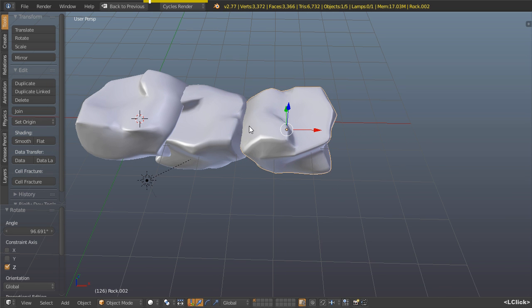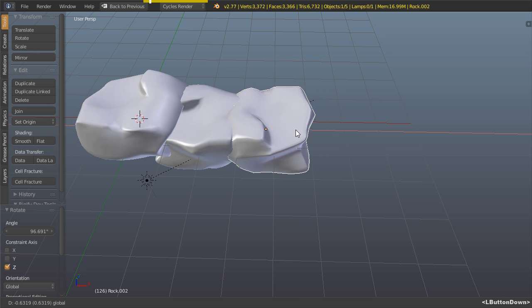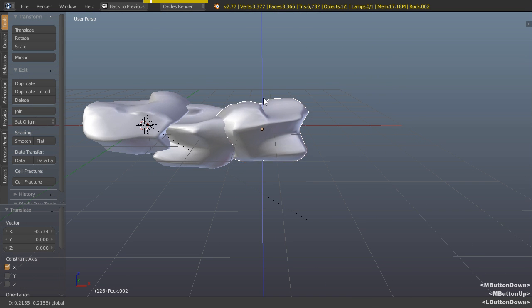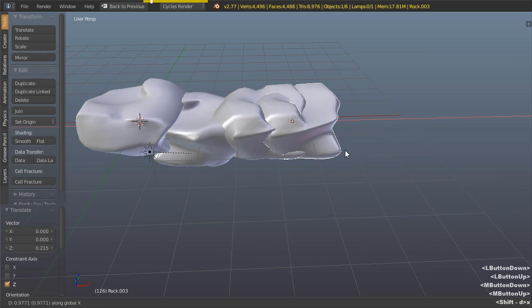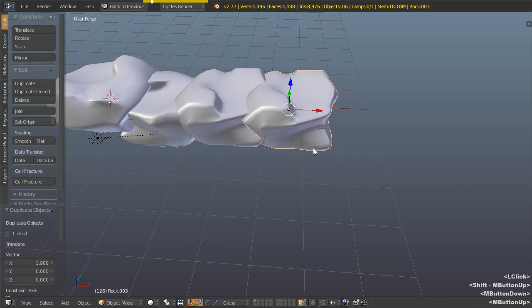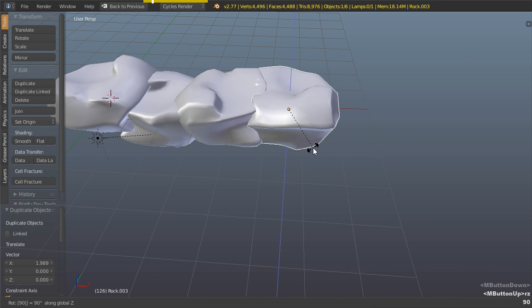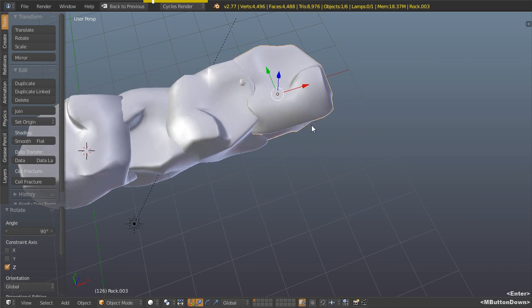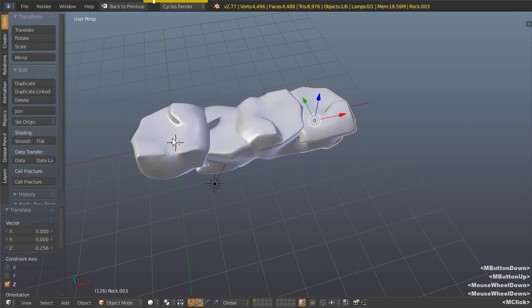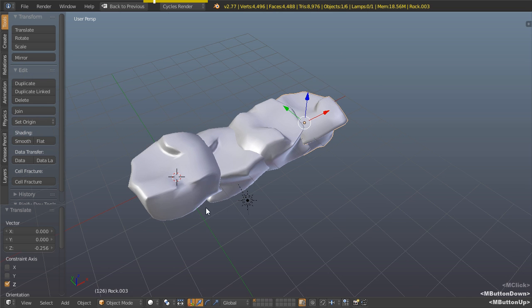Maybe we've gone too far with that, so I'm going to left click and drag that towards about there, and then maybe raise it up a little bit, and then Shift D, X to constrain along the x-axis, left click to drop it into position, R Z just key in 90 on the keyboard there, and let's see, G Z to lower that down a little bit. So those first 4 rocks are into position. Now we're going to step them down.